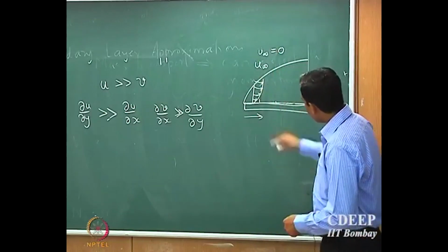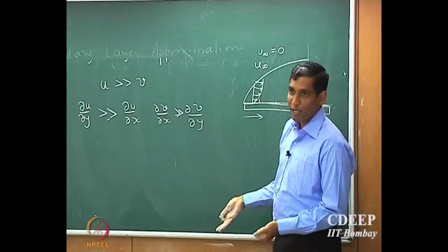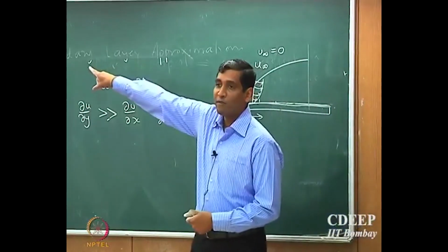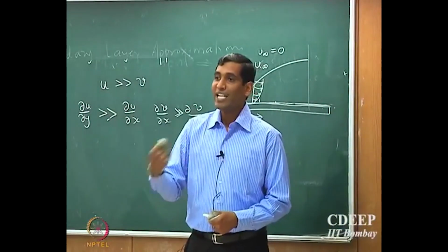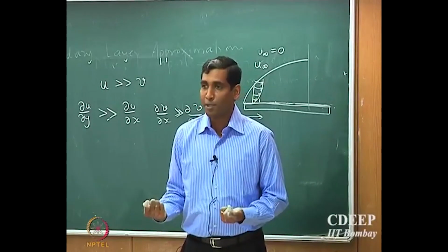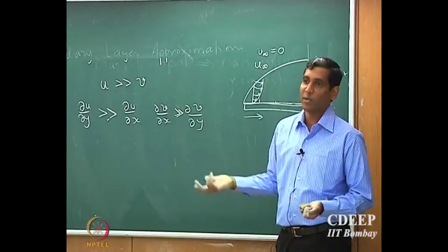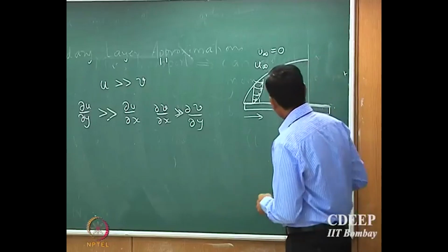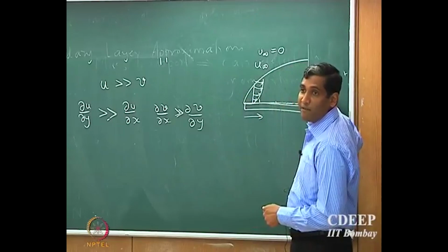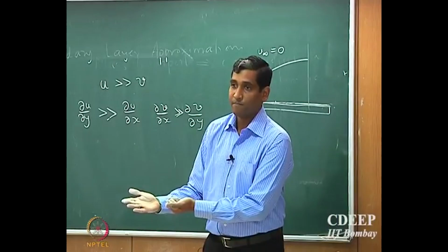But then because some of the fluid particle velocity has now changed and some of them have actually come to 0, right? The x component velocity has come to 0. The continuity equation will force that there has to be a dV by dy, otherwise the continuity equation is not satisfied, and because it's an incompressible fluid, you must have y component velocity in order to satisfy the continuity equation. Now the slowing down or the gradients in the x direction that you will get is simply because of the shear of the fluid offered on itself.